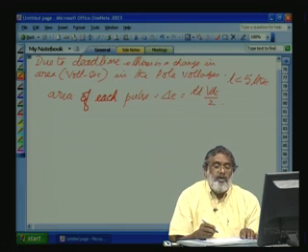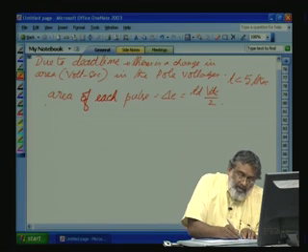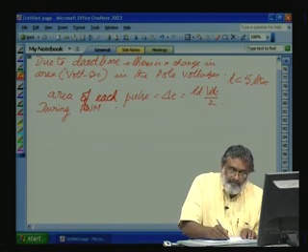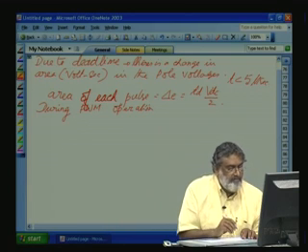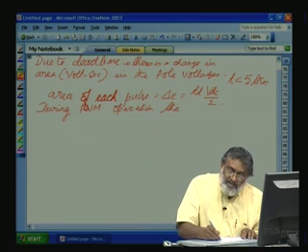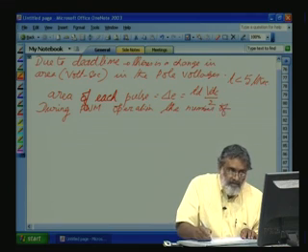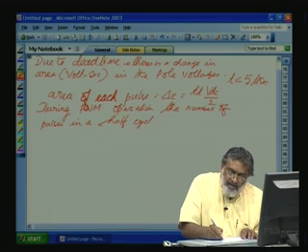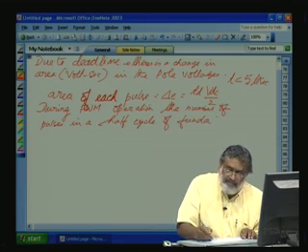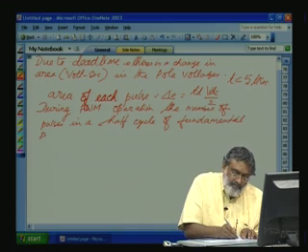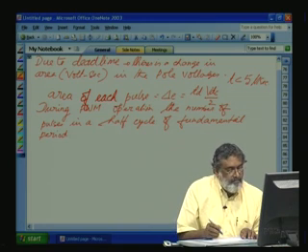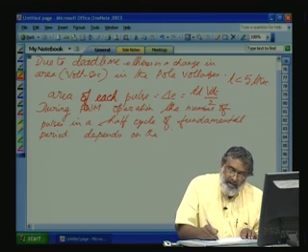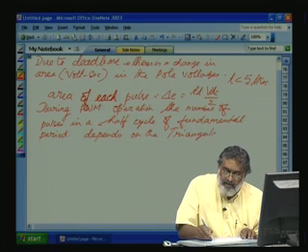But let us take a PWM operation. Maybe in 6-step operation it is okay, but during PWM operation, the number of pulses in a half cycle of fundamental period depends on the triangular period or the carrier period.